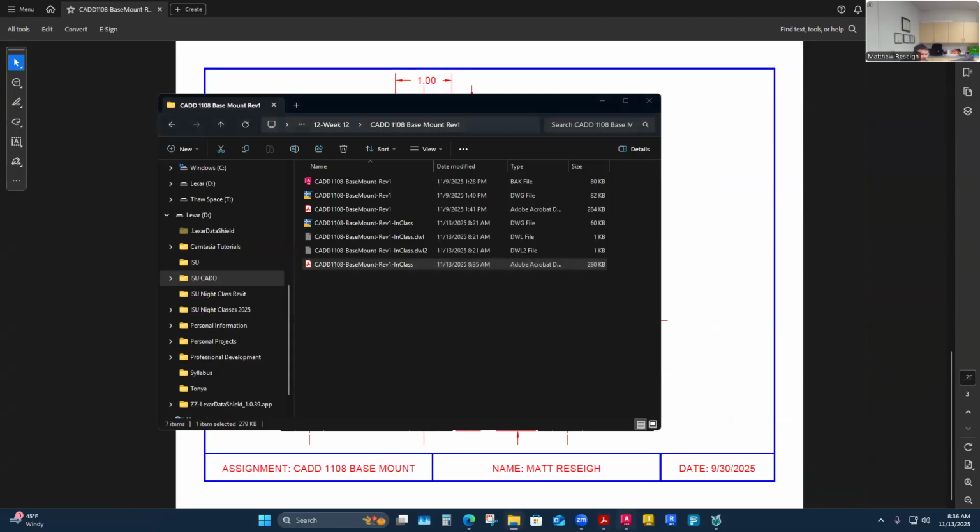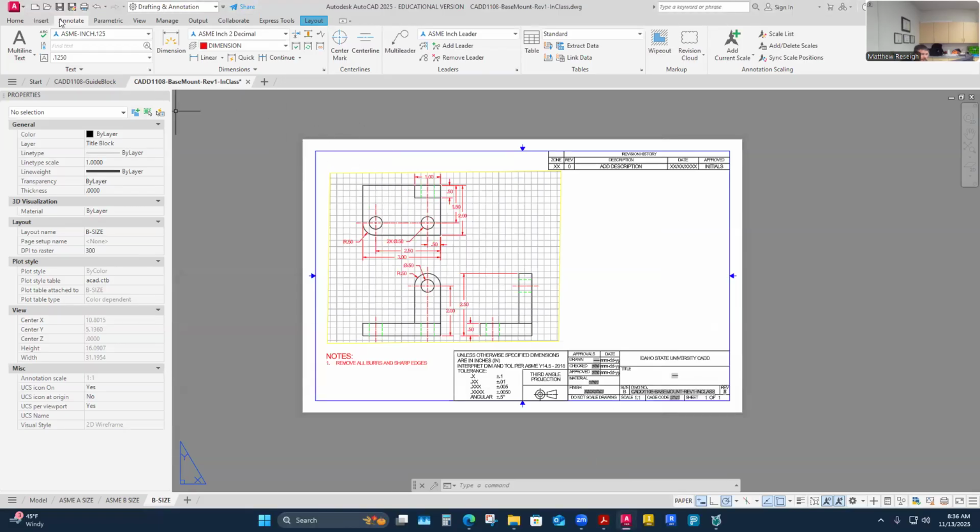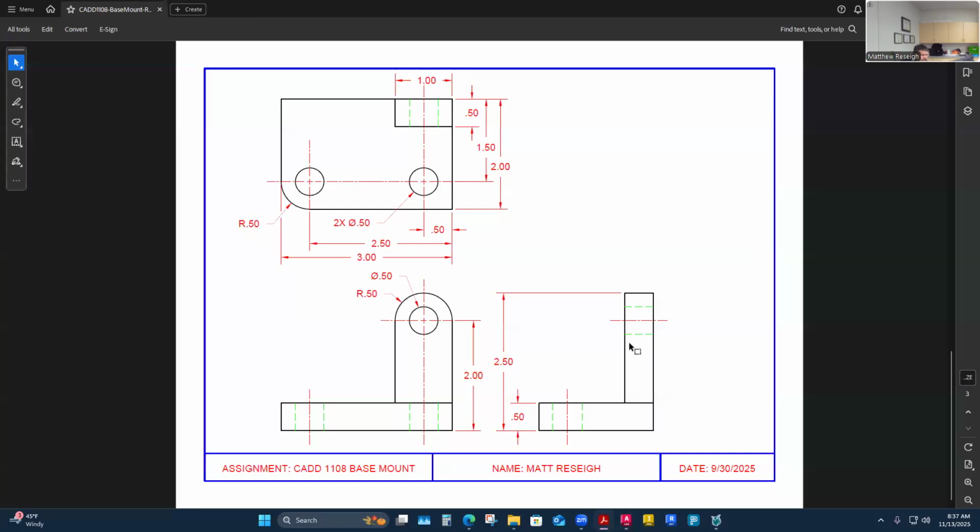Yeah, once I kind of went through and clicked through that batch plot file, and I said publish, I picked my folder first, then I gave it a name in that folder, and then it just put it there. Once I hit OK, it actually just put that thing there. It just didn't open it for me to preview, which is pretty common. I don't know why the batch plot doesn't open up your PDF once it's done. Just doesn't. So then I have all 3 of my sheets here.